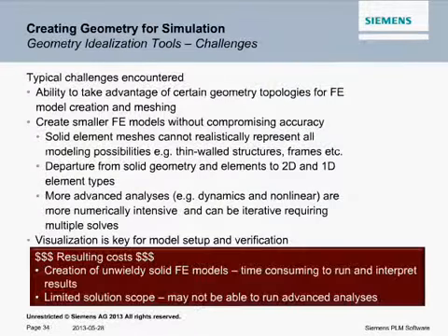So typical challenges then, the ability to take advantage of certain geometry topologies for modeling and creation, creating smaller models without compromising accuracy, so turning solid elements into two-dimensional or even perhaps one-dimensional elements if you're looking at frame-type structures, and just getting away from solid geometry, to create these small, efficient models.